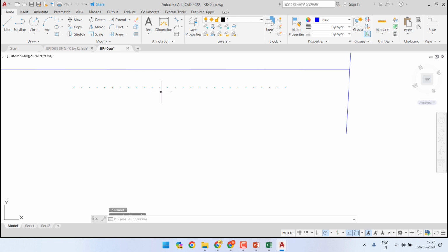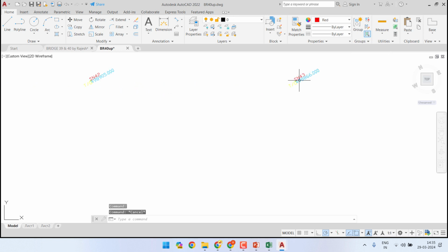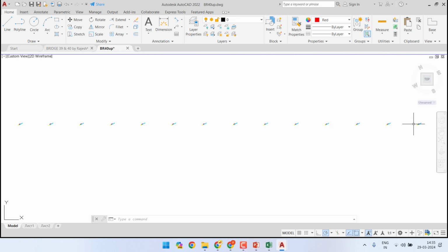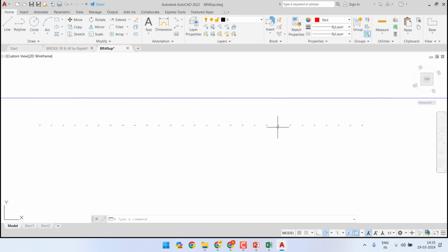Another option was we could select 2 points outside the reverse curve, which are quite far, like station number 43 and station number 37 as good points, draw a straight line, then extend it towards the reverse curve, and then see what is the offset.